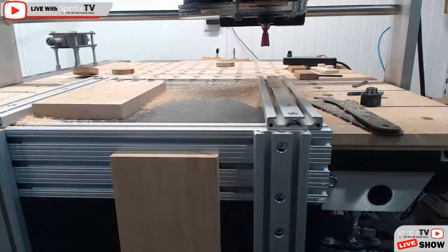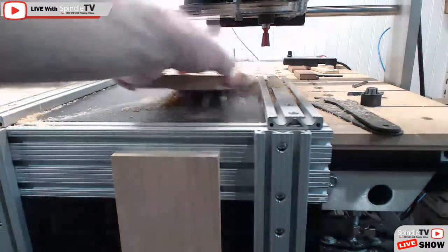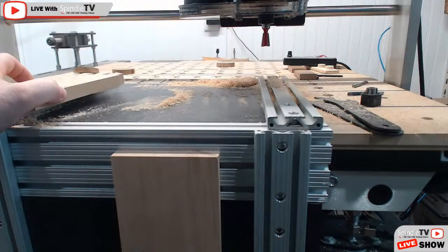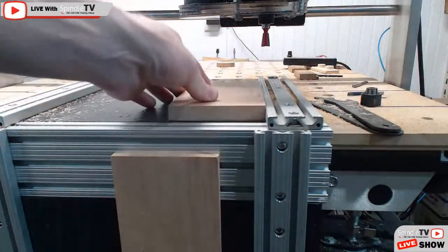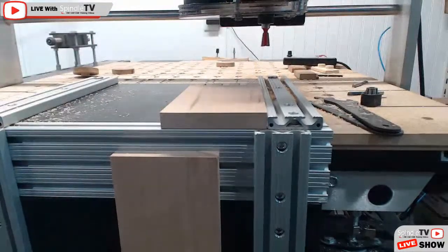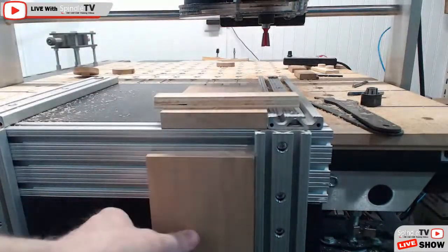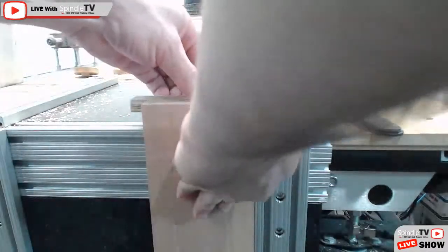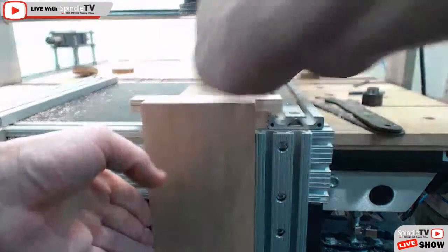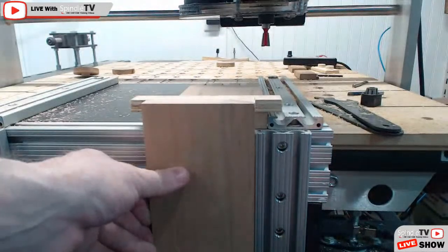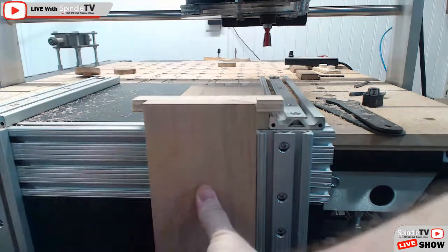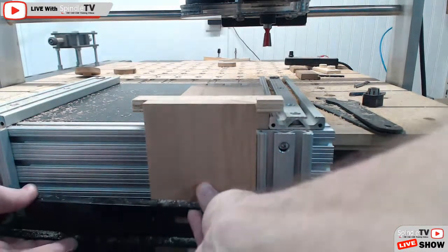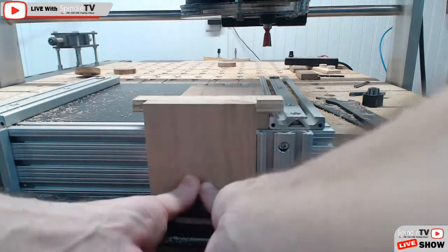Let's move that out of the way. All right, let's see here. Now, once again, sorry, hold on a second. I'll use this piece here as well as my spacer piece, and all I'm going to do is just raise this up, make sure that it's flush, and then I will bring my fence up and clamp it in position.